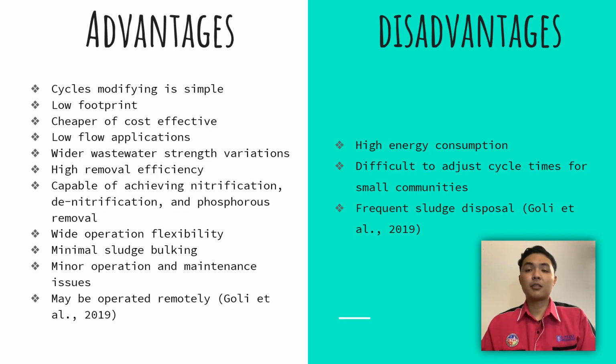For the advantages, first, cycle modification is simple, low footprint, cheaper or cost effective, low flow application, wider wastewater strength variation, and efficiency of removal is higher in terms of BOD, COD, pH, total suspended solids, and total solids. Capable of achieving nitrification, denitrification, and phosphorus removal.